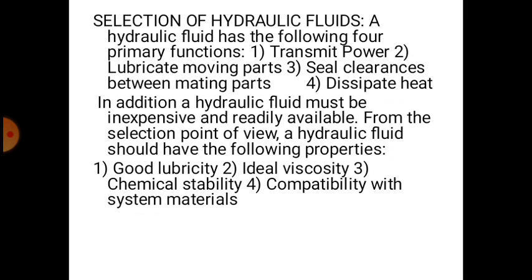So the fluid which is used in fluid power systems has four functions: it will transmit the power, lubricate the moving parts, seal clearances, dissipate heat. In addition, a hydraulic fluid must be inexpensive and readily available.